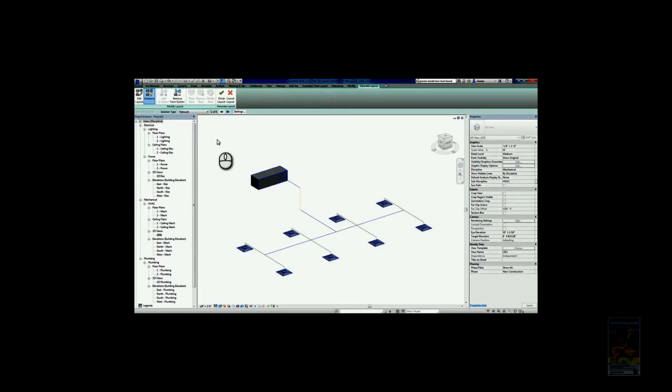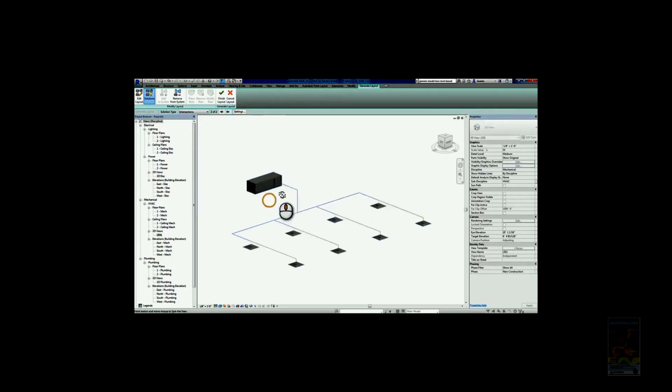What this will do is it will automatically go into solution mode and give you different types of solutions to work with. You have network, perimeter, and intersection. Within each solution type, you can click the little arrow here to toggle between what it thinks makes the most sense for you versus what doesn't. If you don't like what you see, you can always switch to, say, perimeter and try the arrows again and see what solutions they give you. If you're still not happy, try the third choice, intersections. And eventually you'll find something you like.